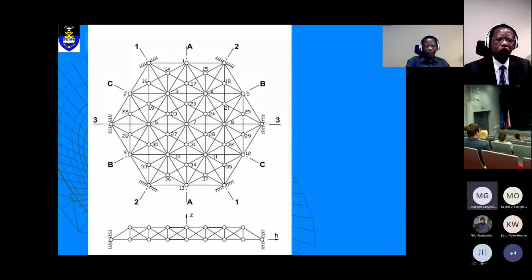The hexagonal grid has 19 nodes in the lower layer, 6 of which are supported. The upper layer is 24 nodes. Thus, we have 37 degrees of freedom corresponding to the small vertical motions of the 37 unsupported nodes. The system belongs to group C6V.